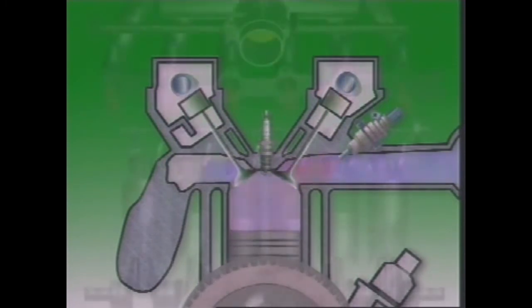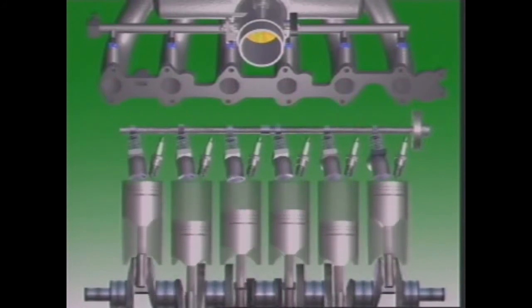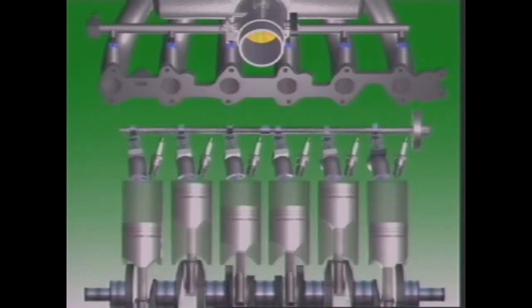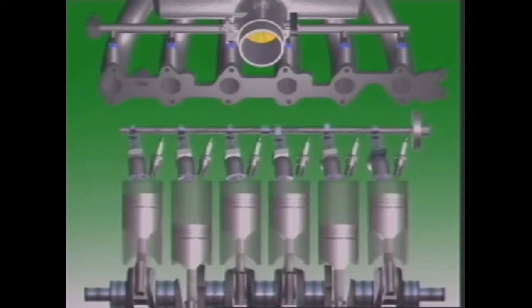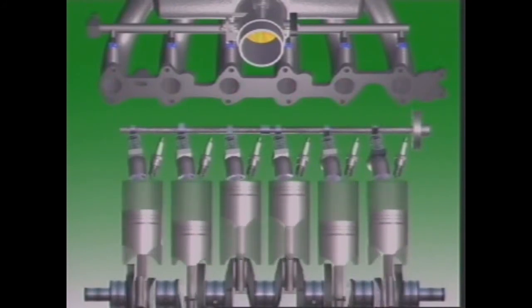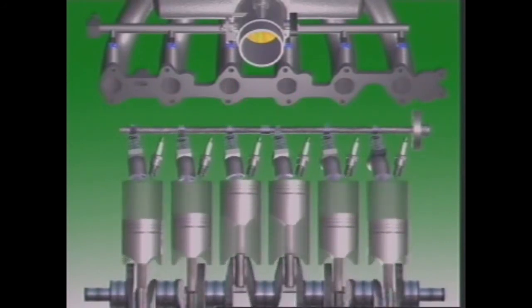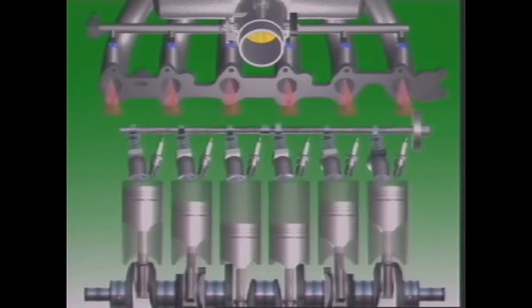During each engine cycle, the injectors open twice, and each time they deliver half the fuel needs of each cylinder. This happens regardless of the position of the intake valve. The injectors are triggered by the ignition system. So, for a 6-cylinder engine, the control unit triggers the injectors on every 3rd ignition pulse.